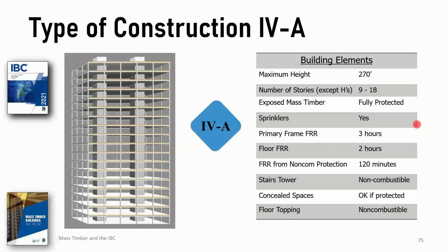If it's a high-rise building, it's required to be sprinklered. If it's a group R, it's always required to be sprinklered. So you can have some low-rise and mid-rise group B, for instance, that may not be required to be sprinklered. But for the most part, as soon as you hit 75 feet, an occupied floor level, 75 feet above the access for the fire department below, the code requires in Chapter 4 that the building be sprinklered. So anything high-rise has to be sprinklered. Same with mass timber.